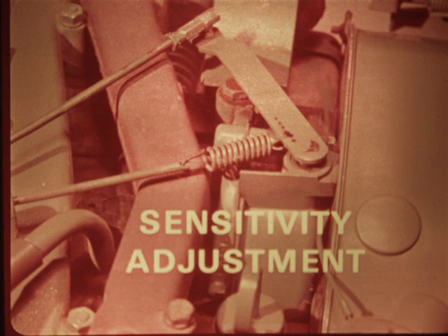The final engine adjustment is the governor sensitivity adjustment. This changes the spread in RPM between no load and full load operation, and also may take out any roll that the power adjustment didn't correct. Factory settings, however, seldom require adjustment.